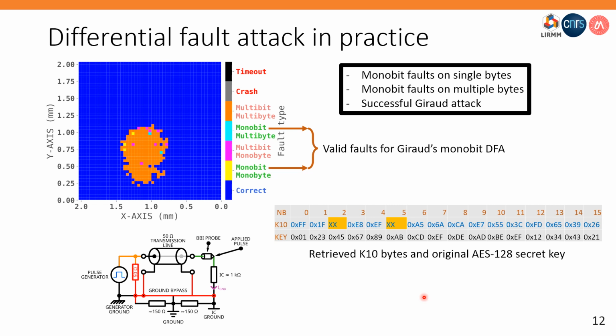However, despite all our efforts, it was impossible to recover the last 2 bytes, the numbers 2 and 5 more specifically, thanks to this fault attack in any of the 5 locations. Nevertheless, with 16 bits left to find, it's only 2 to the power of 16 combinations in the worst case scenario in a brute force attack, considering that our platform computer can perform 180,000 encryptions per second. It would take less than a second to find the remaining bytes.